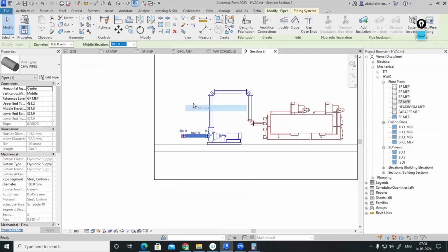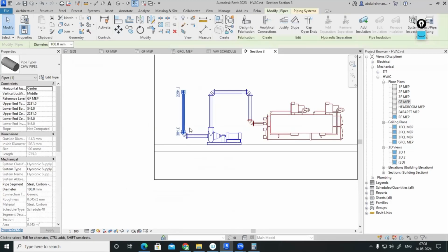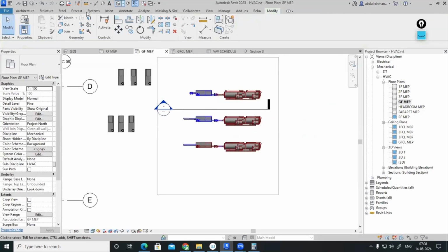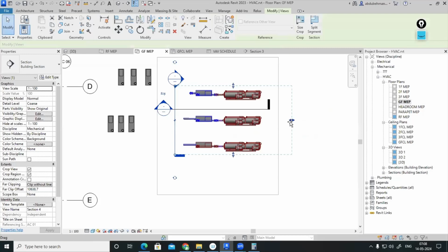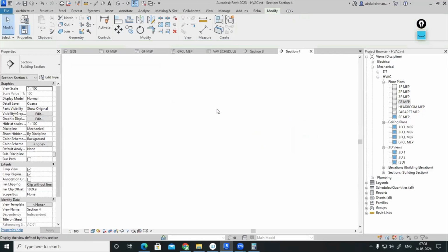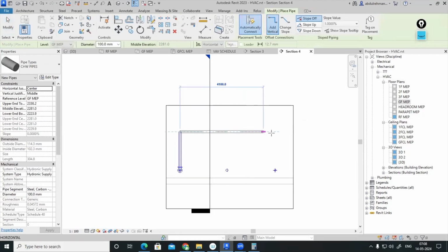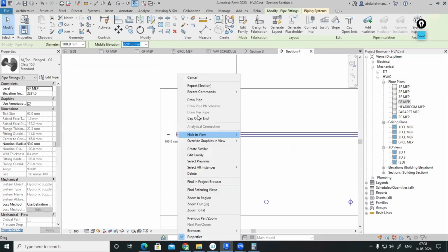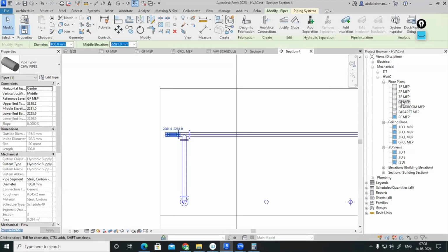Okay. So what I'm doing, I will be making a vertical pipe. This is my suction header only. Suction line. I'll be making very near to the pump. Here in the vertical, I'll be connecting the pipes. And let me make a section in the front side also. Okay. Now make it fine. This is my suction header. Okay. So I'll be making this as a T-joint. From here, I'll be making a pipe slightly here. And you can cap it. Okay. That is my suction header.